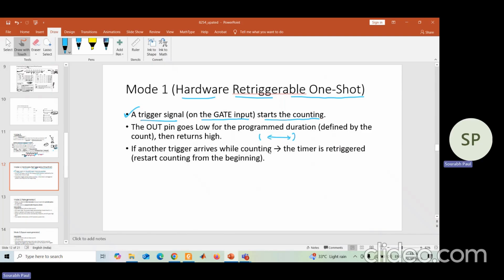Okay, so when you have started the operation, suppose your count n is equal to 4, so you want to do a count of 4. What will happen in this case? The output terminal of whichever counter you have selected will generate this type of signal. What type of signal? When you have loaded this value n equal to 4 to the counter, at that time the value of the output terminal is high. Now, when the count operation is going on, at that instant its value will be low.